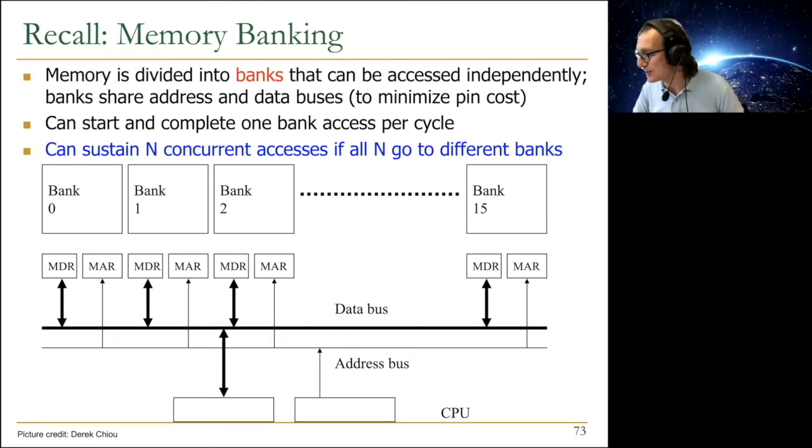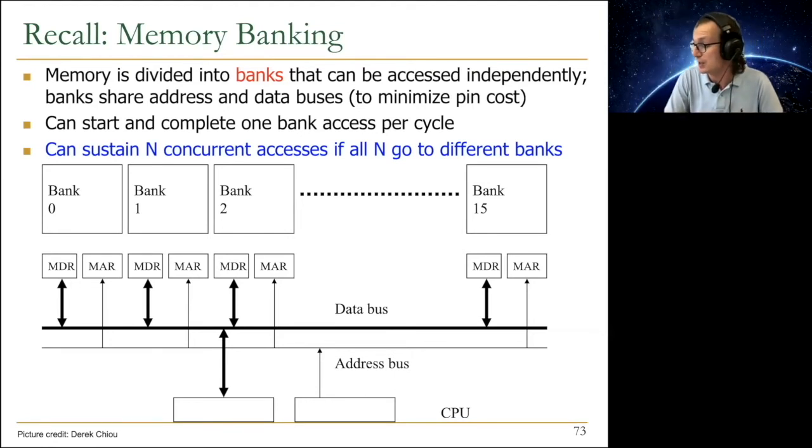Okay, there's one question. So is a certain part of memory reachable only by a certain bank, or is this assigned dynamically? I don't quite understand the question here. So all of the memory is reachable by supplying the bank address, row address, and the column address, right? So the memory controller needs to supply which bank you're accessing. And each bank has a partition of the memory, basically.